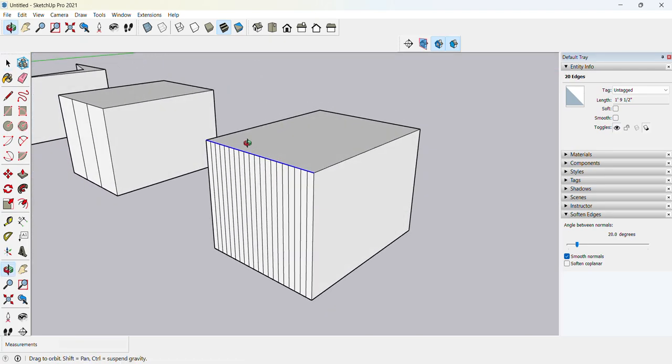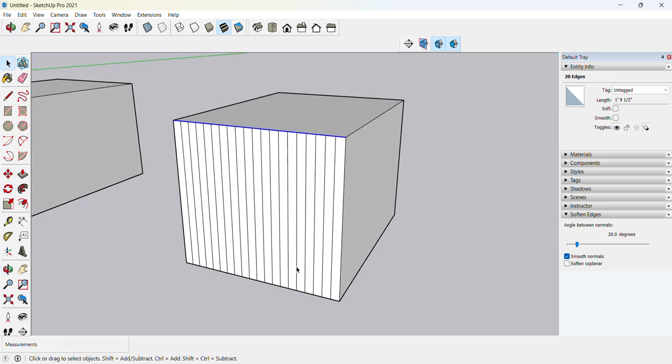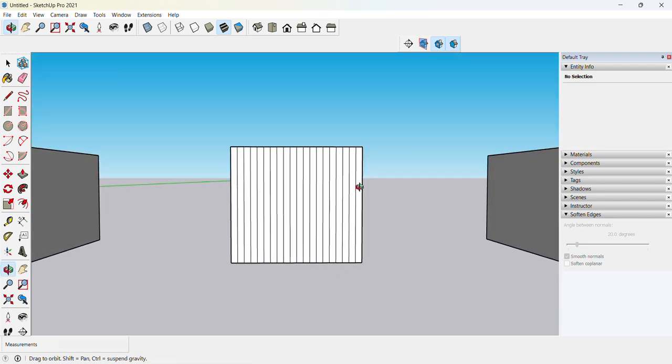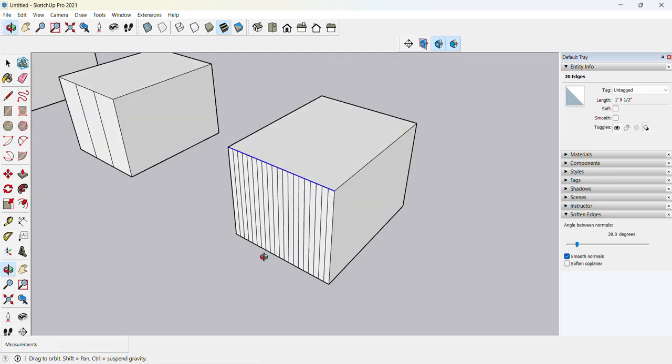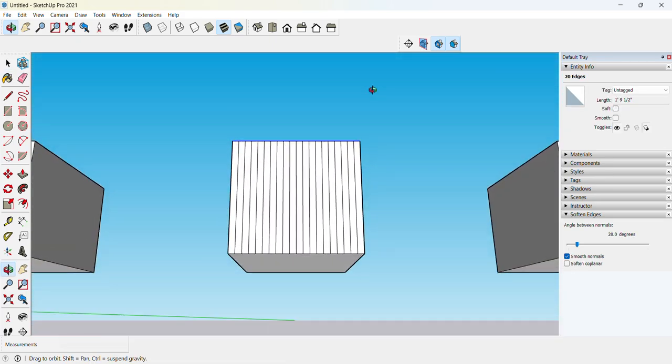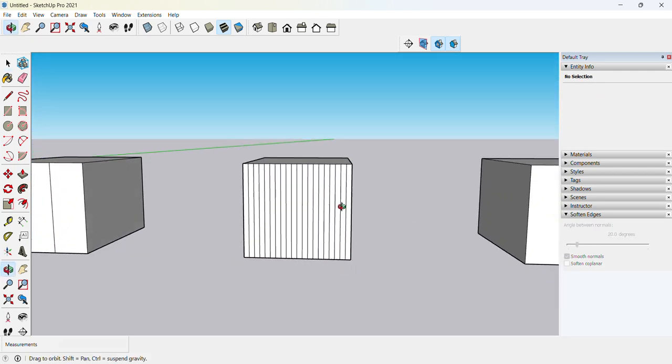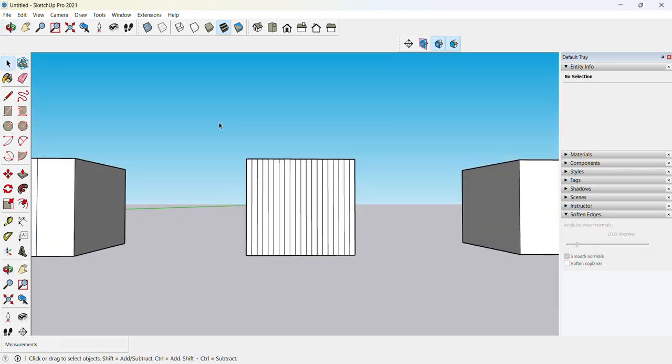Okay. See here too, I want to divide this vertical surface into 4 divisions. For that I am selecting M. This is my base point. So once again I want to show you how I select all of these segments. I am taking a window selection for this. Have you seen? I just want to adjust my interface firstly.